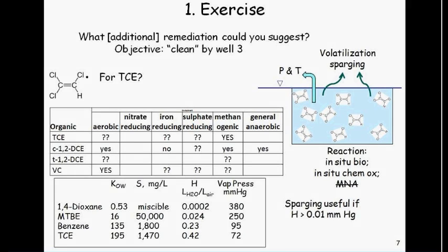Well, again, pump and treat. Of those chemicals, TCE is the most hydrophobic. It's the least soluble and has the highest KOW. That's still not a huge number, and we could pump it and let desorption work, but it's not going to be as successful as it would be for the other chemicals.